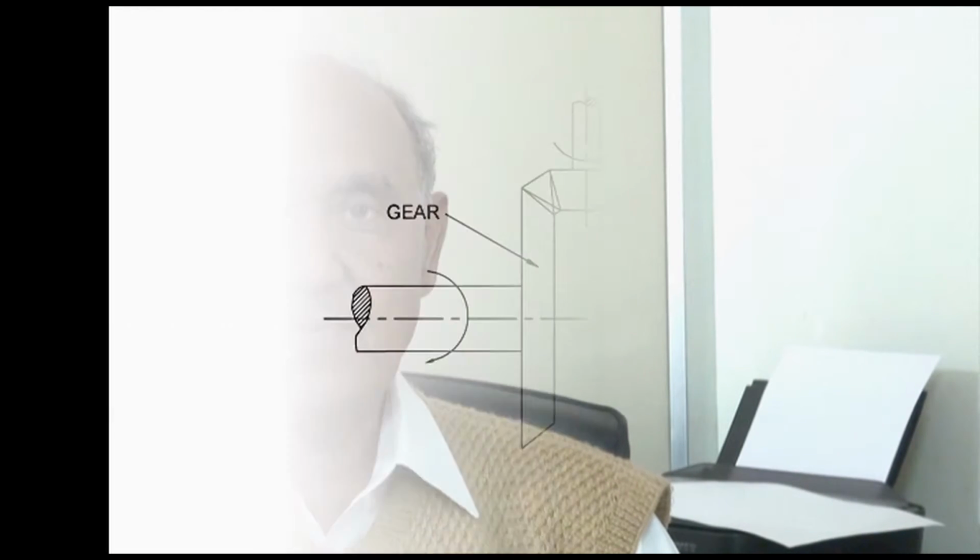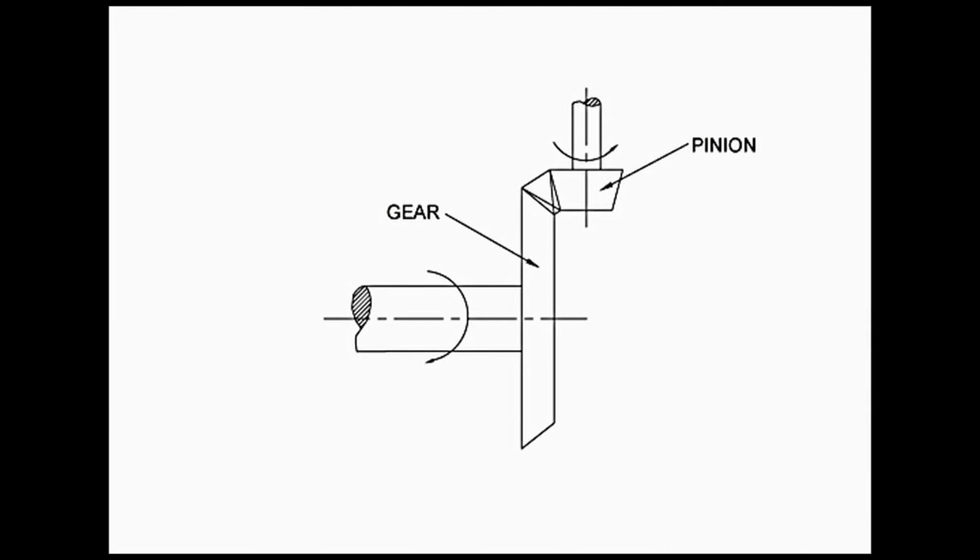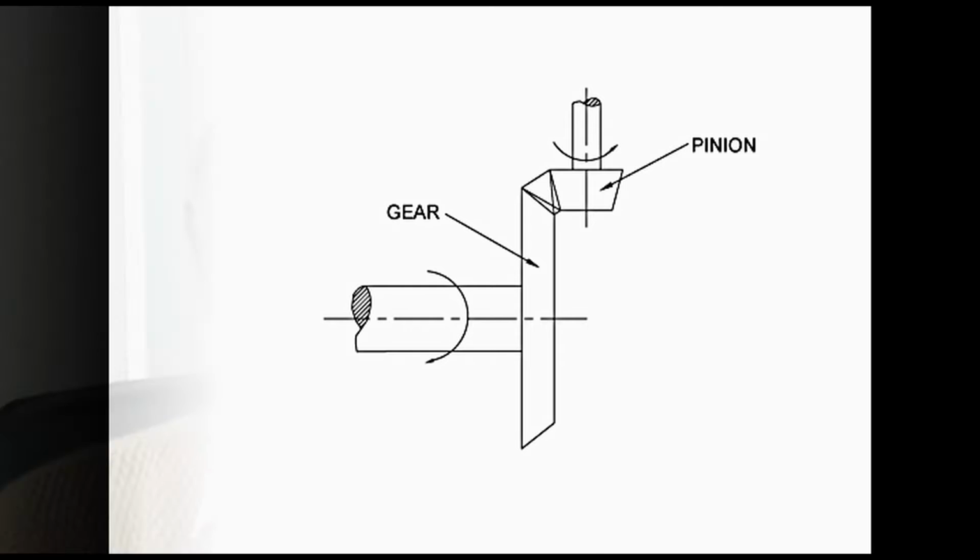Now, where we are transferring motion, that axle is known as live axle. So this is done with the help of a pinion and gear. We are all familiar with the pinion and gear system, and this is used for transferring motion through 90 degrees. Another important function that is performed by the differential is when the vehicle takes a turn.